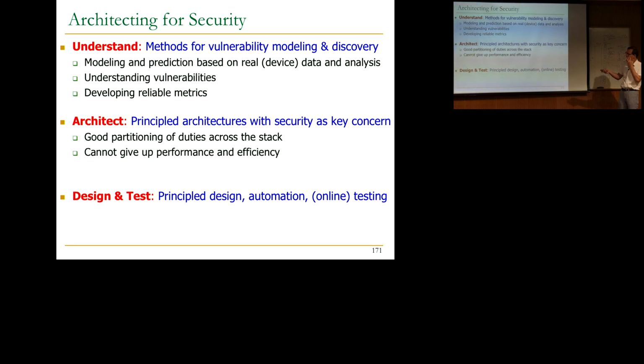Of course, while we are doing this, we cannot give up performance and efficiency. I think patchability in the field is very, very important, as we discovered with Rowhammer. If you have a memory controller that's patchable in the field, you can do a lot more. I think Flash has this beautiful characteristic right now. Its controllers are patchable in the field, right? You have controllers that are essentially processors. Well, some of them are hardwired, but it's relatively patchable compared to DRAM.